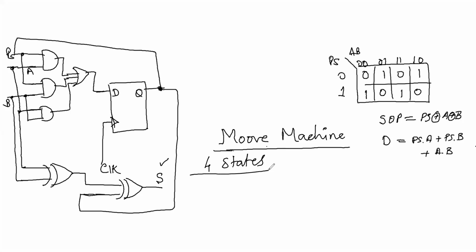It's very simple now. Half of the task is done. It's very simple because it's a serial adder. An adder has 4 options: with your carry in or the partial carry 0, your sum can be 0, sum can be 1. Similarly, with your partial carry as 1, your sum can be 0 or your sum can be 1. So you can easily write all the transitions corresponding to the 4 states. You will have 4 states for sure. You only need to draw their transitions.